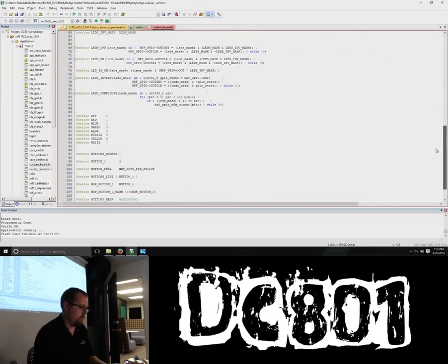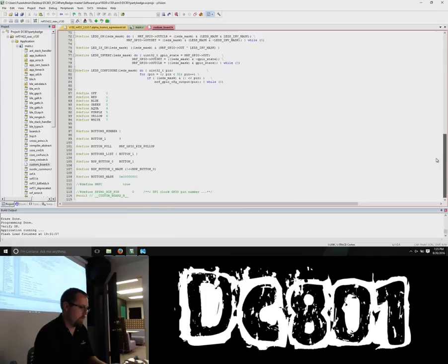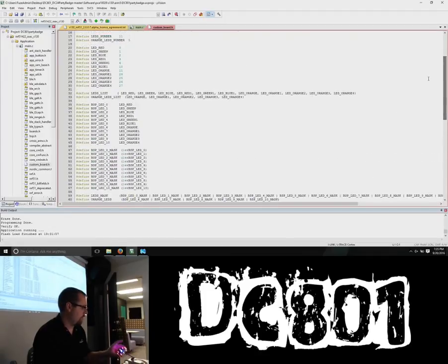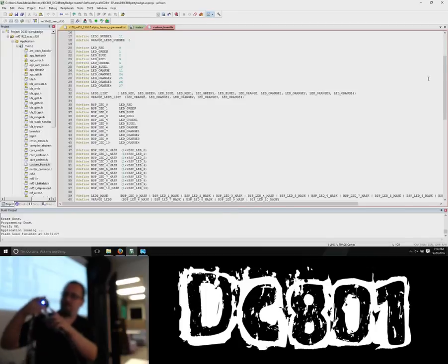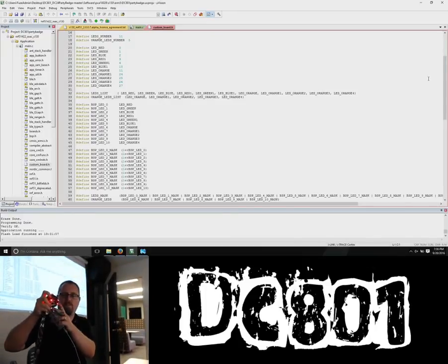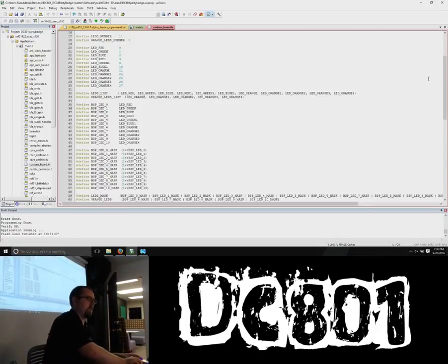So all this has all the pinouts for what's on the badge. We do have 3 pins that you can play with on the party badge that are off, looking at the right hand side. That is a full I2C bus. Right over here, that's a full I2C bus and an extra pin for clocking or other things that you want to do with it. So they're full GPIOs that you can solder and connect to and add them into the H file.